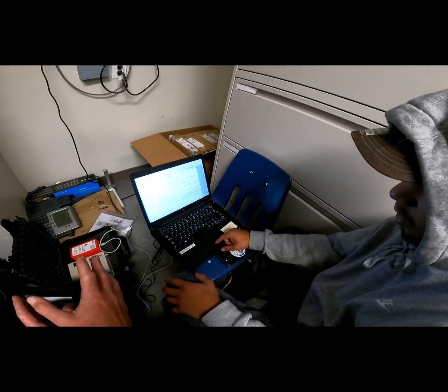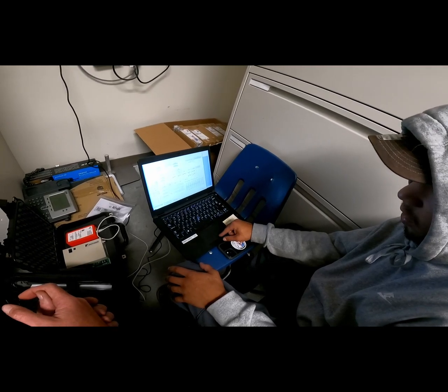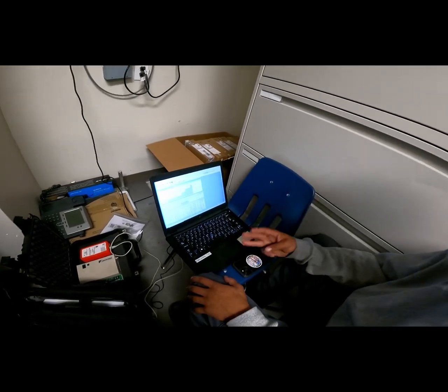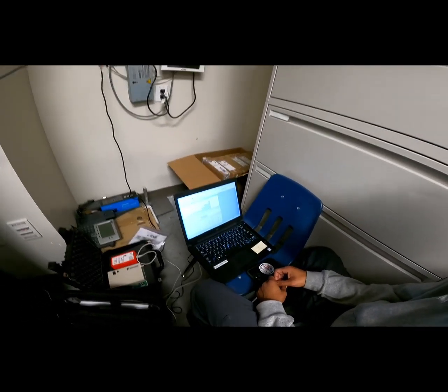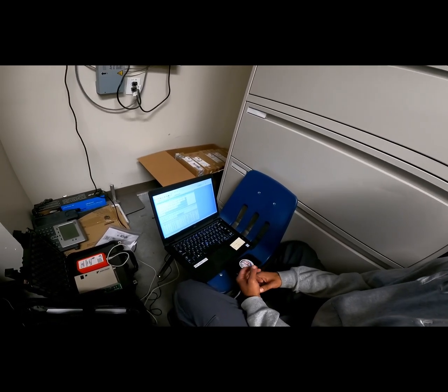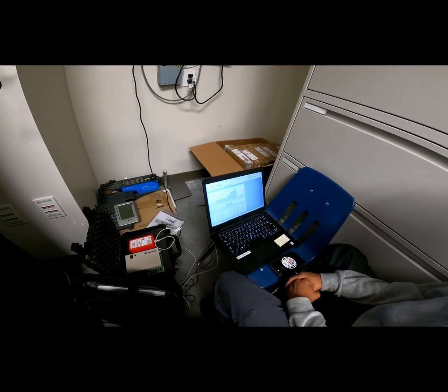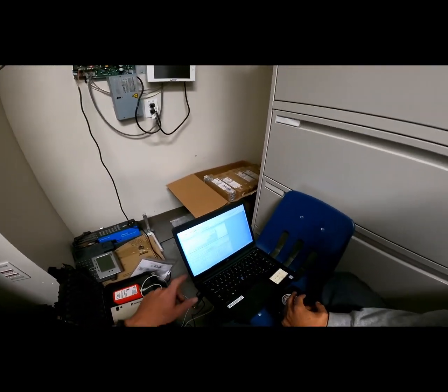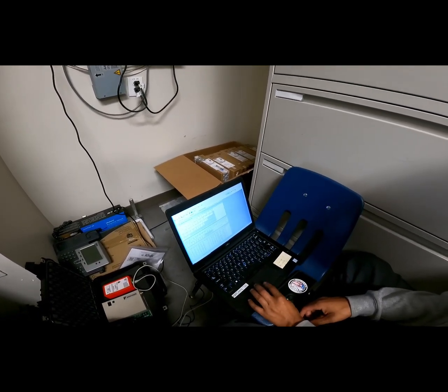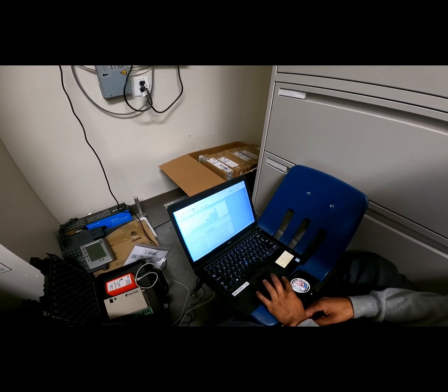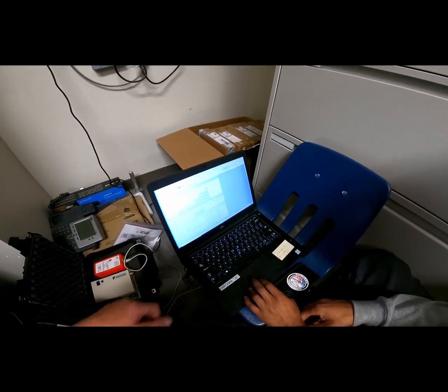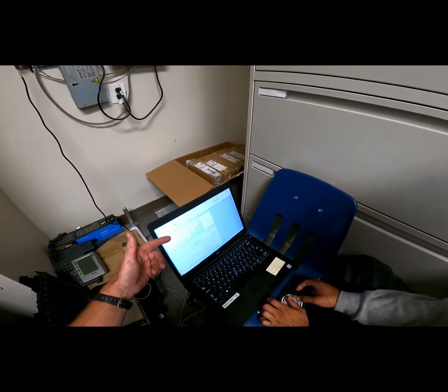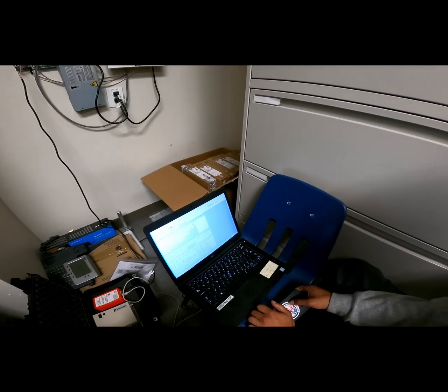All right, so once that went through, go ahead and close that window. Now, can you see up here how many minutes we've been monitoring this system? So we've been monitoring it for 3 minutes, but now we're about to go into full test mode. One way you'll know that that outdoor unit is running, if you left click on IU right there, what does it say that is? Phase U current. So that's the current of the compressor in the outdoor follower OS.